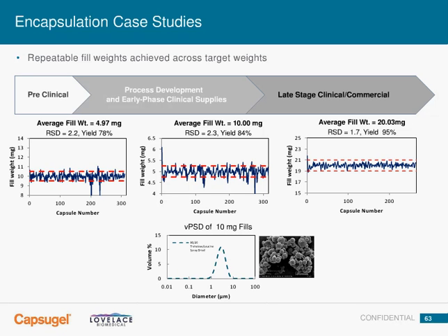What's shown on this slide is excipient-filled material. I think this is a trehalose leucine placebo, with a mean particle size of about 2 microns. Certainly one of our worst flowing or worst handling materials, which we want to use to really challenge the system. What's shown here is 3 different fill weights, common ranges we might see for an early phase clinical study: 5, 10, and 20 mg fills. You'd say active loadings of, let's say, 10 to 50%.